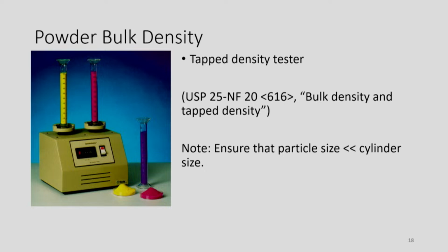So commonly it is one sample instrument, but for grains and large materials there are large cylinders that allow us to tap a big volume of powder. You can load the samples in cylinders, fix the number of taps you want, and then get the change in volume and get the tap density. Okay.